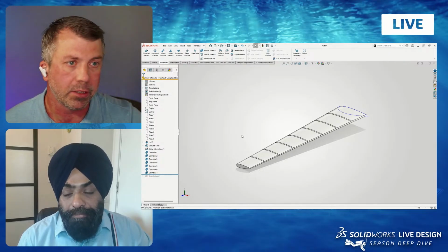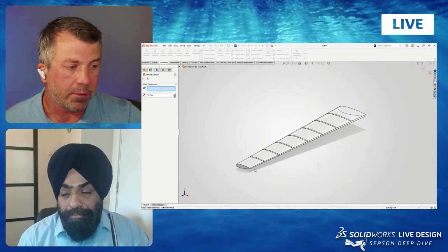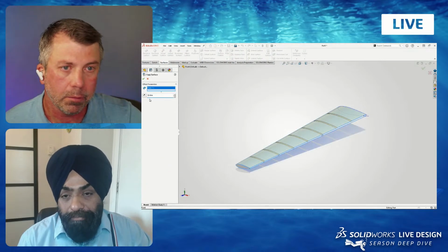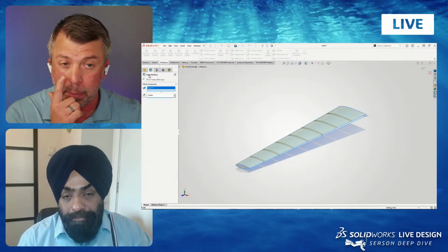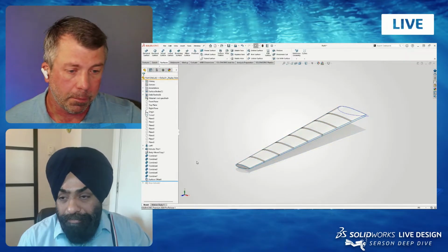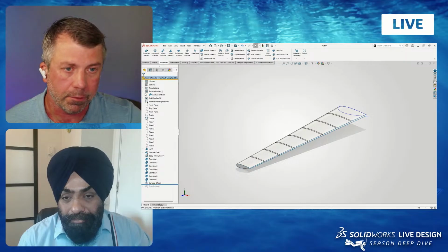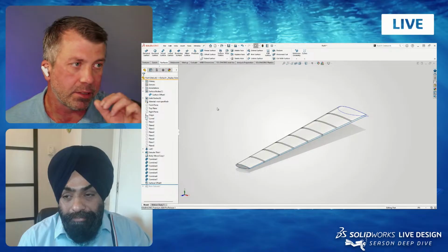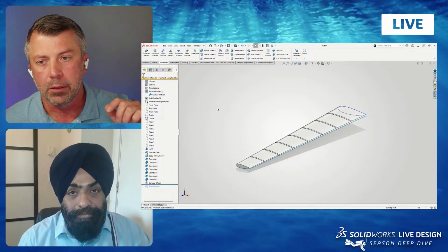So using a surface, you could still do it later on that initial extrude. Surface loft is a nice way to do it. Here, I'm just going to do an offset surface, and we'll grab that wing dimension, and we'll say it 0. When I say 0, it turns into a copy surface. And now I've got a surface body that represents our wing. And the only thing I'm going to point out is it does require a complete flattened surface.